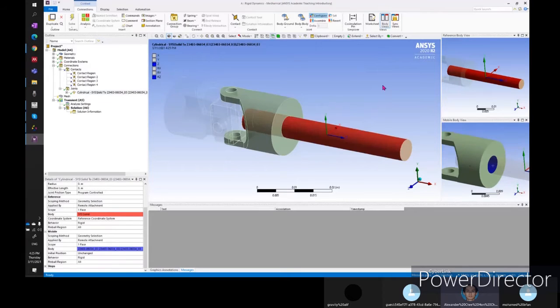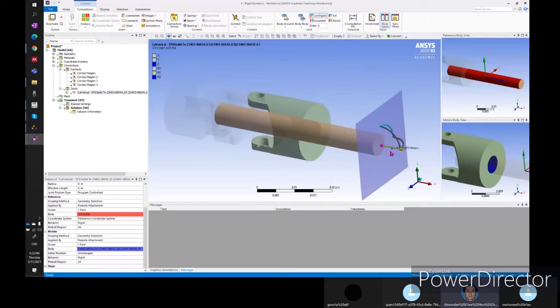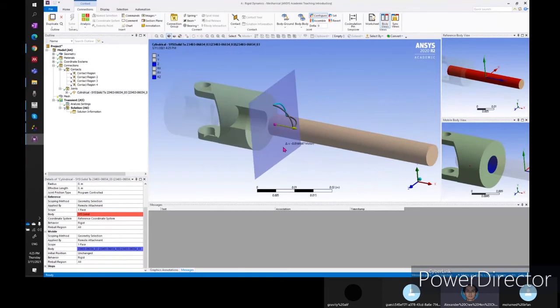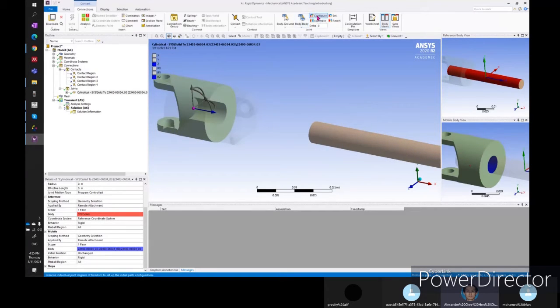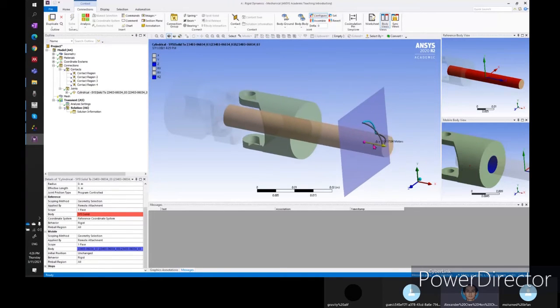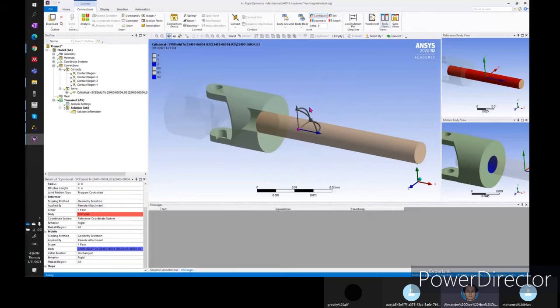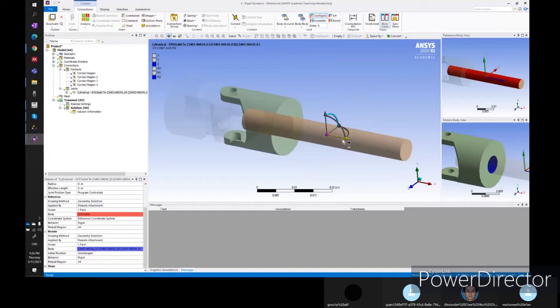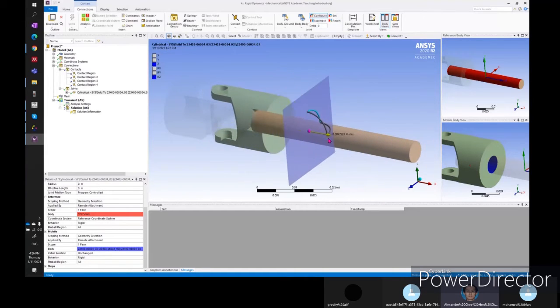After that, you can click one more time and test this, so it can also have this translation. You can just depart them, no problem, because once you close the configure, they go back to original. By that, you can study the other joints and how they define the relation between part and part. That's how it is.